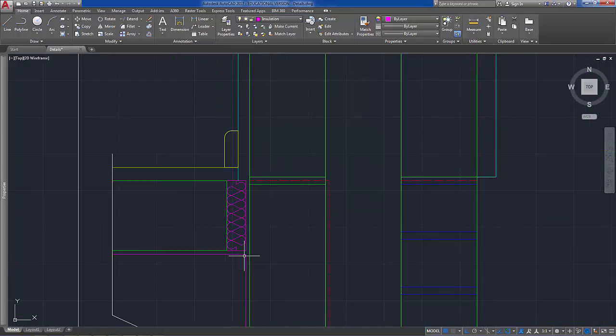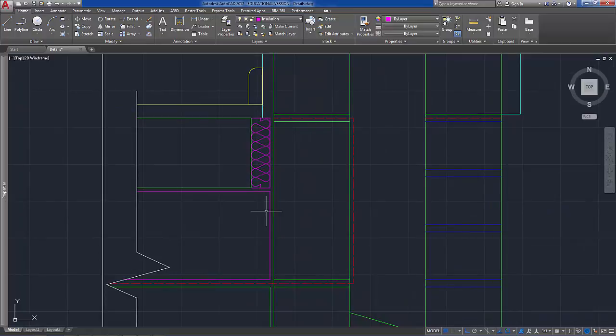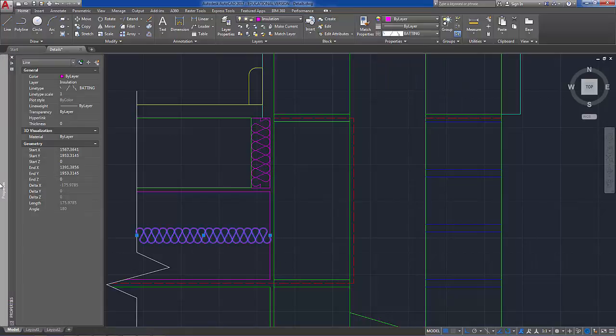Okay, so that might look okay, might not be to everybody's preference, but it is something that will work in a lot of circumstances. But let's apply it over here and see where there's maybe sometimes a problem. So again, we'll go and choose the line type and change the scale, with that being 125. Let's check.